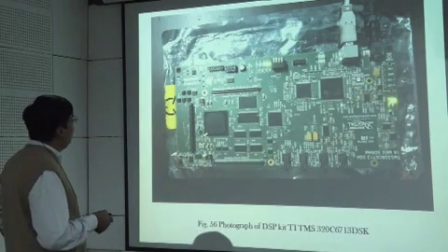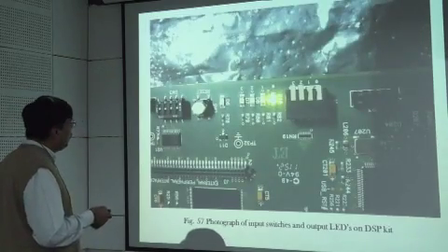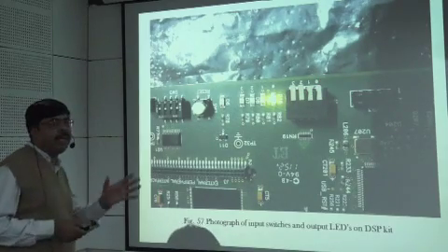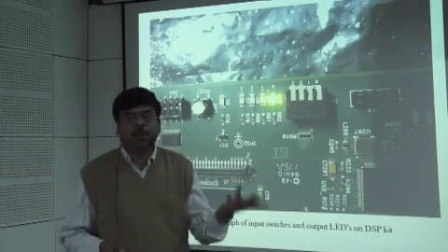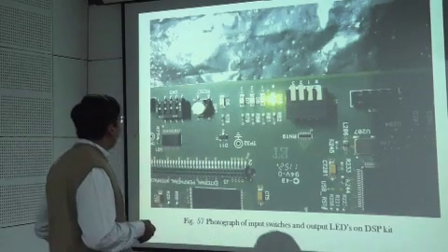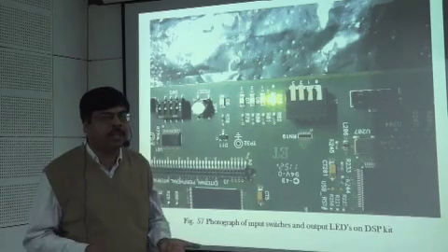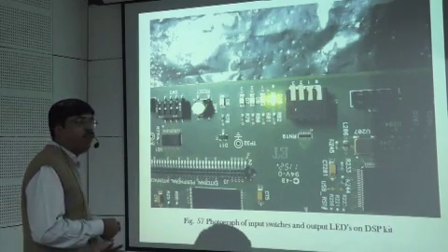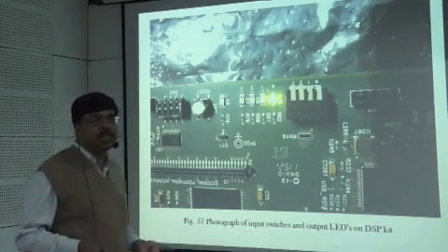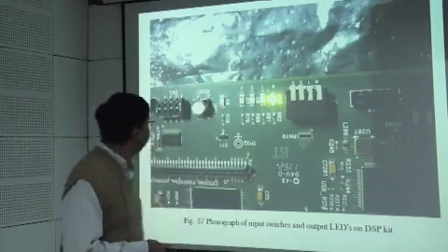It has 4 input switches, which means at a time we can test 16 types of possibilities on this DSP kit. There are 4 output LEDs, out of which the first LED has been configured for the non-fault condition and the second LED is configured for fault conditions. The DSP responds properly for my algorithm.